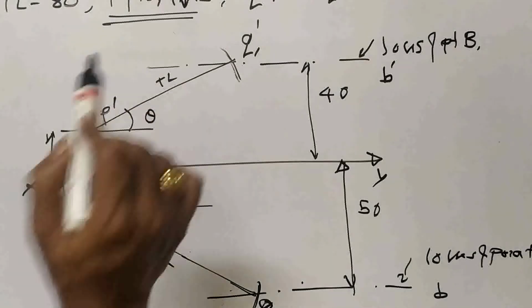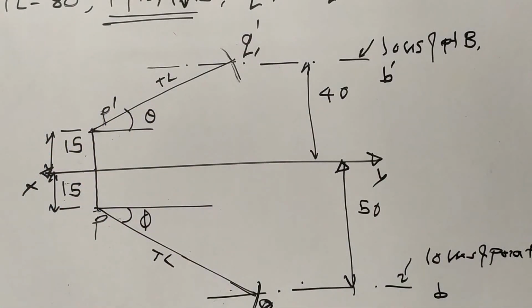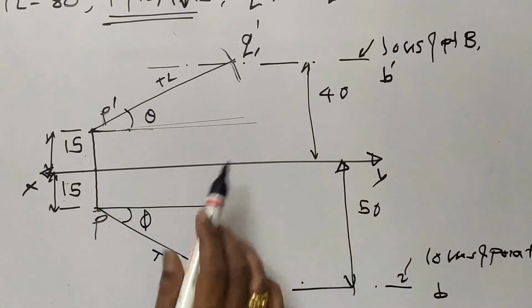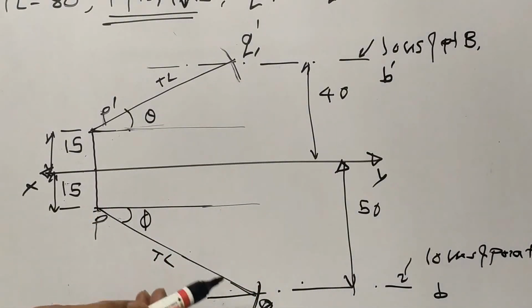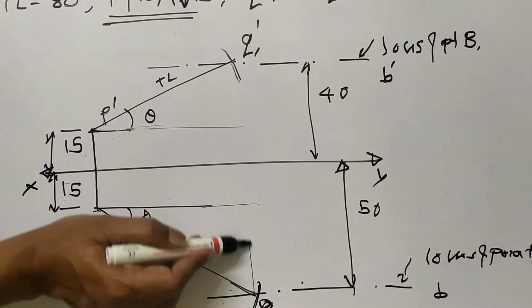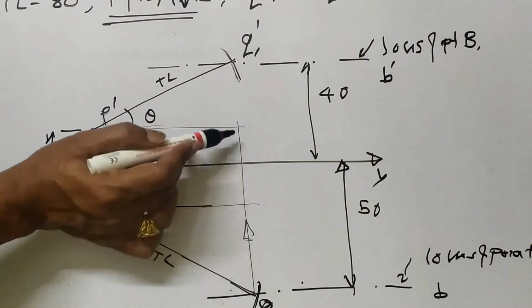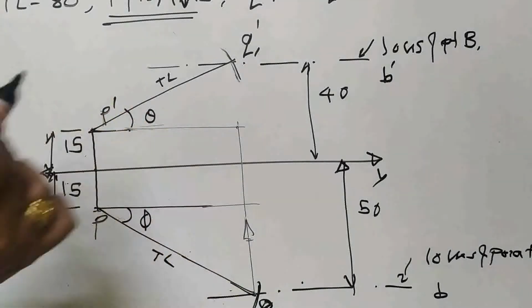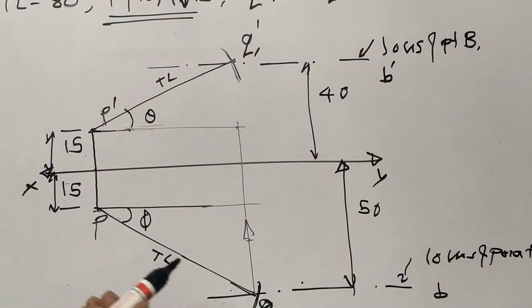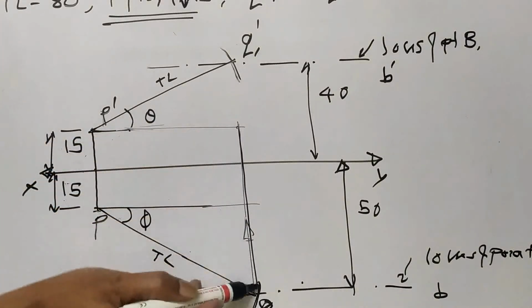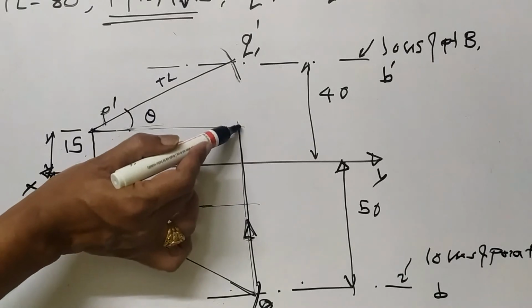Now I want elevation length and plan length. We know the map reading concept, that is true length is converted into plan length and elevation by projection and rotation. So what I will do, I will project this true length up. So I will draw a perpendicular line. So this is perpendicular to XY up to this. So this is a projection, and then take this as a distance in the compass. Okay, so this is the projection line, and then I will rotate it. It cuts here.